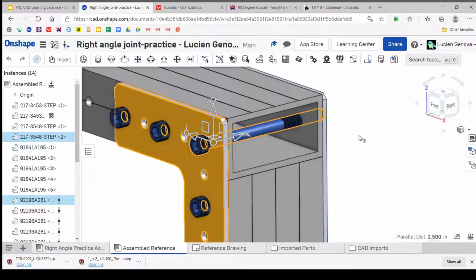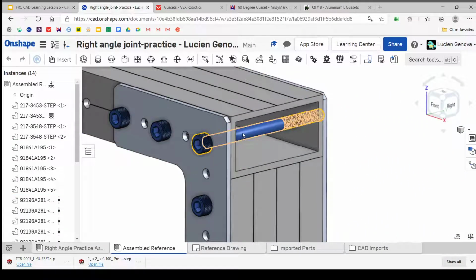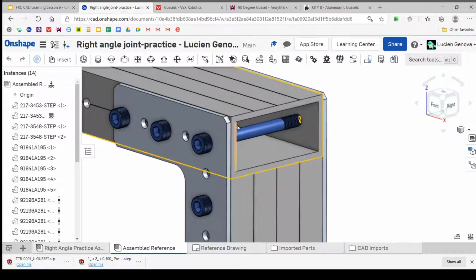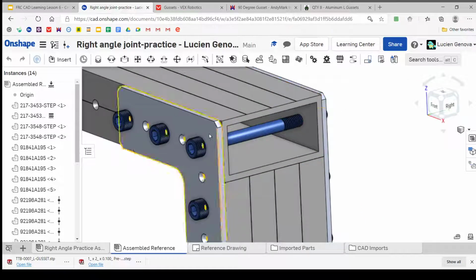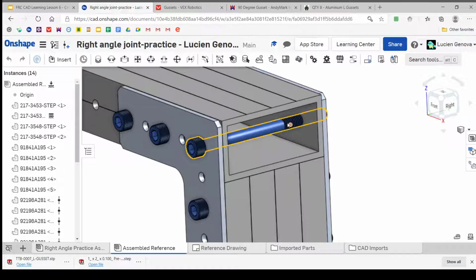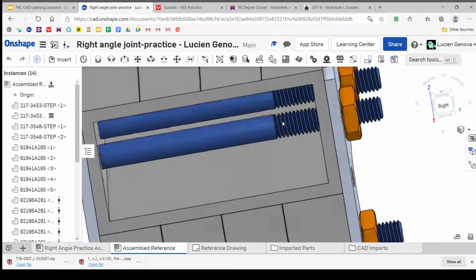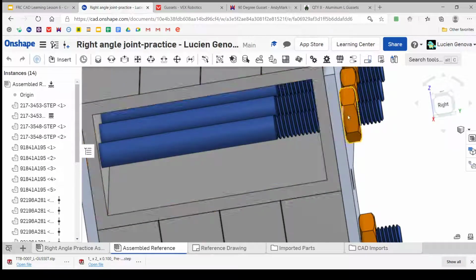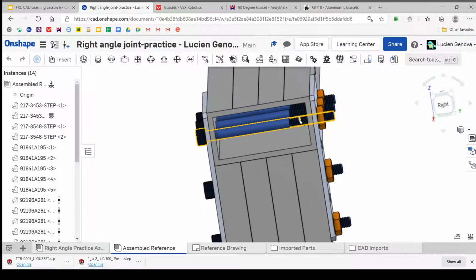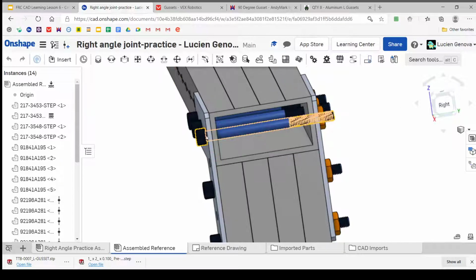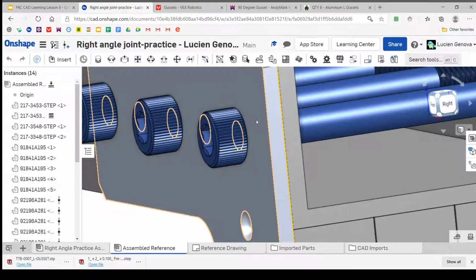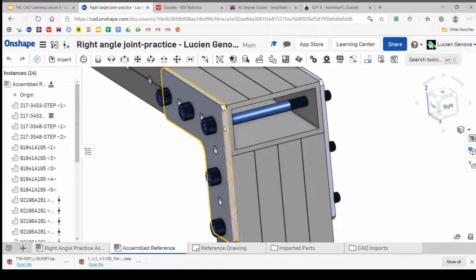It's a 2.5 inch 10-32, right? We know that from the diameter, from the thread count, and, well, we didn't count the threads, but we're going to assume it's a 32. 10-24s are also used, but not by us as much. You can sort of just see by looking at it, right? That looks a little bit more of a fine thread than a 10-24, which would have much coarser threading. And the bolts are measured from the start of the shaft, not from the end of the head, right? Not from the end of the socket head.